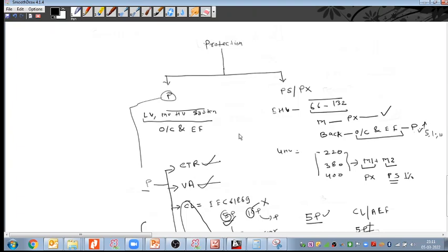What will happen when the connected burden is more than the burden mentioned in the CT secondary, that is, the CT nameplate? The core may saturate. When we were discussing, we were saying what will happen in case of a power transformer.